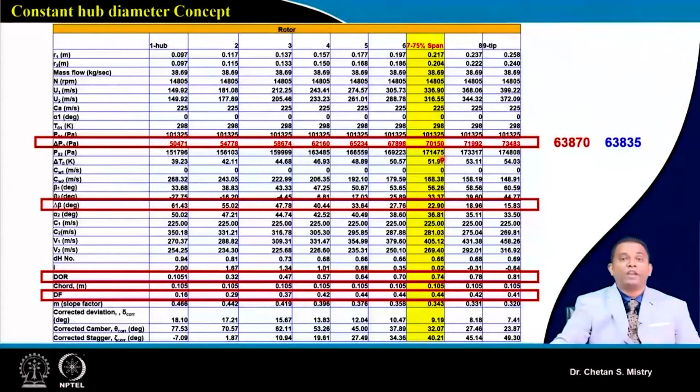Now we do not have any configuration saying what the tip clearance will be. Suppose this is known to you, then accordingly you need to adjust your delta P0. If you recall, when we were discussing the subsonic compressor design, we configured it considering the tip clearance to be 3% or 2%. Accordingly you adjust your delta P0 such that the pressure drop or loss happening near the tip region gets compensated. Once this is configured, we know our C2 and our alpha 2, and that will be the input for my further design of the stator.